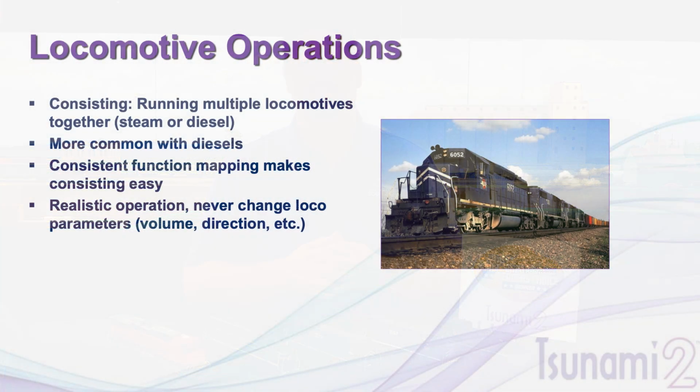And then the other one is called CV211. It's slow speed compensation. If you have a gearing mechanism that's kind of catching a little bit more frequently, you can adjust for slow speed compensation, 0 to 100% equals 0 to 255 value in the CV. So if you have a locomotive that you notice surging a little bit at slow speeds, play around with that, and that'll help eliminate a lot of your problems.